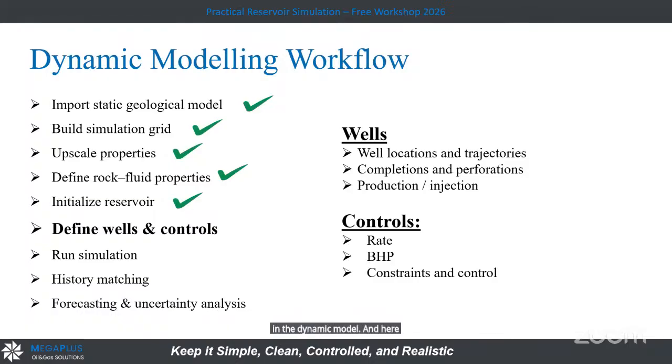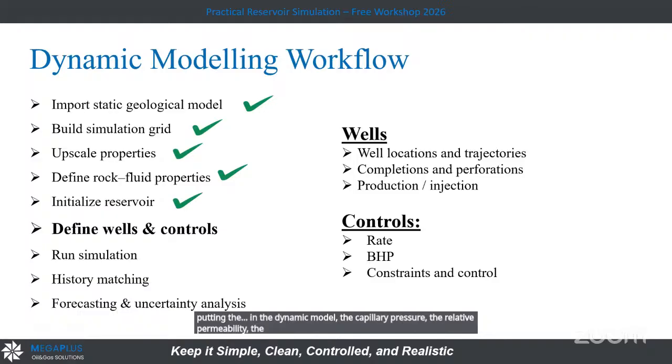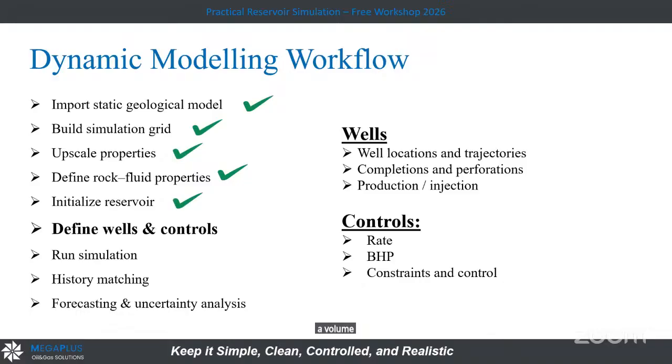And here, before we go through this workflow, in the initialization milestone step, when the static model is finished, we agreed yesterday that I have an output of volumetrics. I have the volume. After I make the initialization, putting in the dynamic model the capillary pressure, the relative permeability, the datum, the pressure, the saturation distribution, all of this, it will give me a volume according to the curves and the new data that I insert.